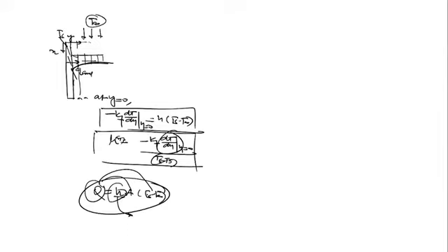Actually, we are more interested in the calculation of the rate of heat transfer, because I told you already it's very difficult to develop the temperature distribution. Here you are seeing a very simple case, there are many complex cases where the heat transfer coefficient comes into the picture. I will discuss. And what is the importance of heat transfer coefficient? Now your question should be, sir, if we are calculating the rate of heat transfer through conduction, like Q conduction is equal to minus Kf into dT upon dy at y equal to 0, then what is the need of heat transfer coefficient?